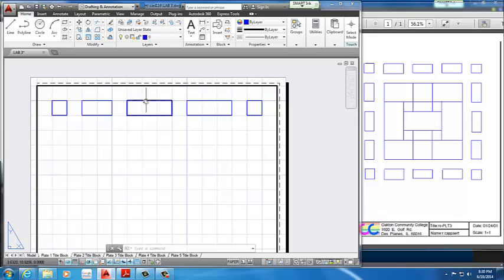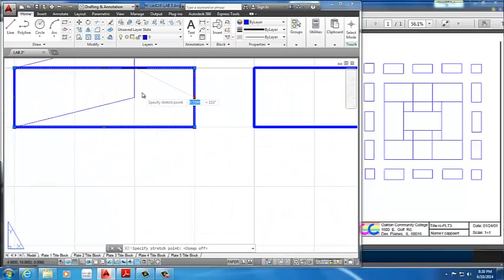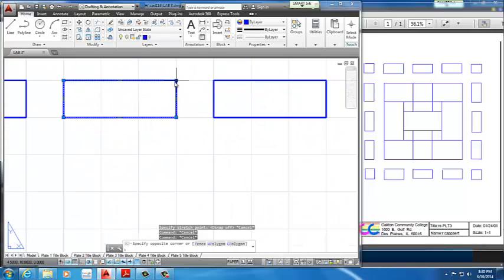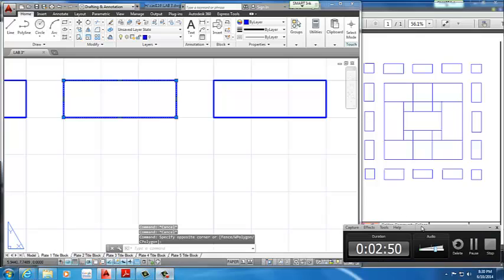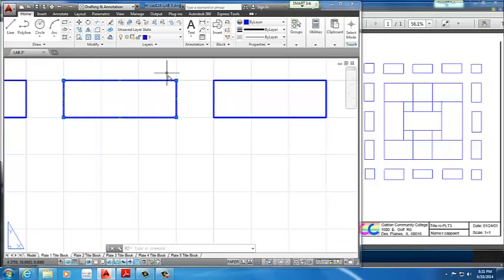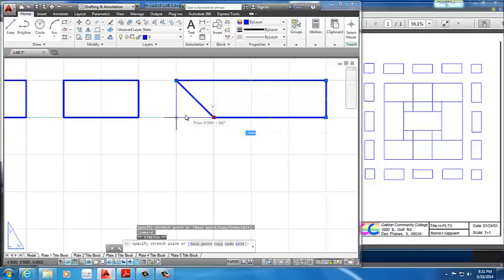The nice thing about the rectangle is that you can select the rectangle. I didn't actually have to hit rectangle. Just click that blue center point right here, marking, and just drag it across and down. Have snap turned off. 1, 2, 3, 4, 5, 6. That looks about right. What you want to do is click the two blue points and just drag them back to reduce the size. Do the same thing on the other side. And I have something like this.